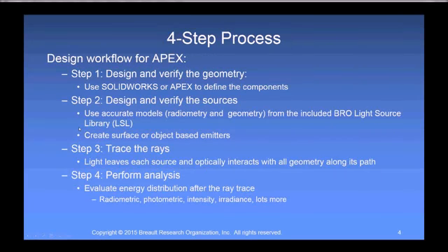So now let me briefly talk about this four-step process, the design workflow for Apex. The first step is to design and verify the geometry. Most of the time, you're going to define the basic structures, whether they be faceted reflectors, smooth reflectors, freeform optics, etc., or mechanical structures that hold things in place.